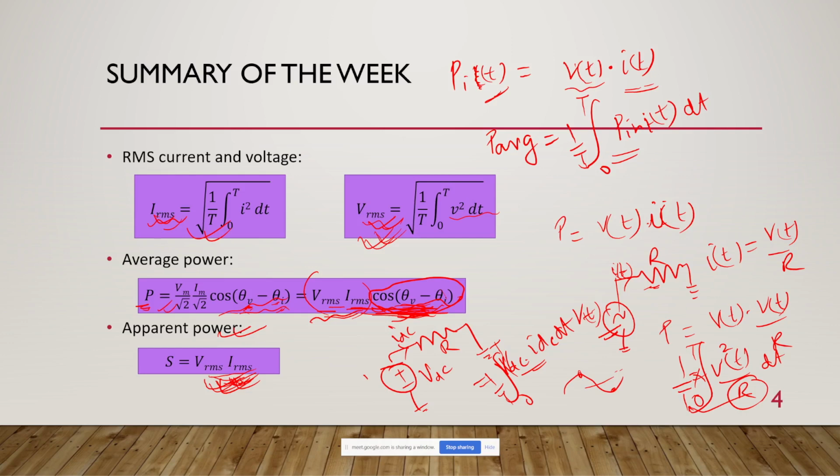Right. So basically that exchange. In one half cycle there is power dissipation, in another half cycle there is power generation. So that is constantly being exchanged, right? So there is no power dissipation, so there is no power surplus anywhere. Whatever you are giving it, it is giving back, isn't it? So there is an exchange going on always, and that exchange is represented by the reactive power, Vrms times Irms times sine of theta v minus theta I.